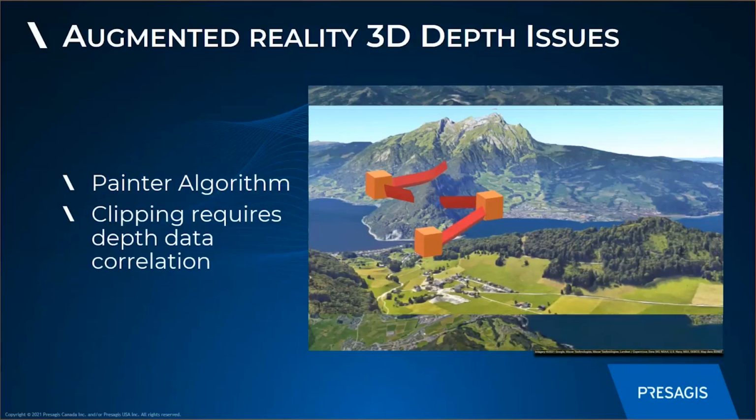It showed you a set of waypoints, but in fact, either the pilot input them incorrectly, or they need adjusting, or there's been an error in correlation. The reality is that if I tried to fly those waypoints, I would have a problem because the altitude between them would mean hitting the side of the mountain. This is a very obvious case, but it's been designed on purpose to show this problem.